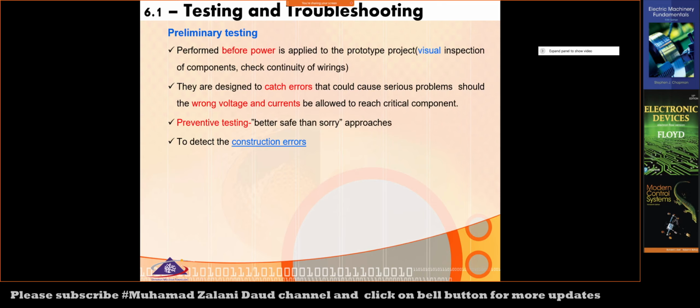Before you switch on or provide supply to this prototype, what you need to do is to check the connections and the continuity of the wiring. So what you can do is move the dial to the setting where you can hear the sound, and you need to place the probe to common and the resistor level, not the voltage level. And then what you need to do is to check the continuity.